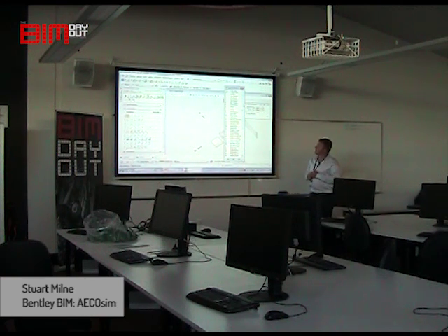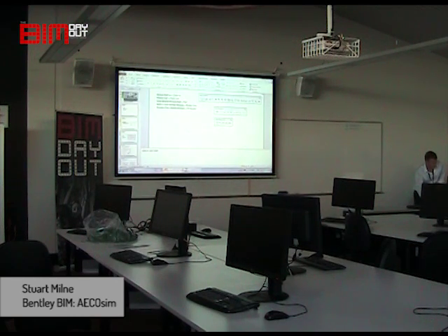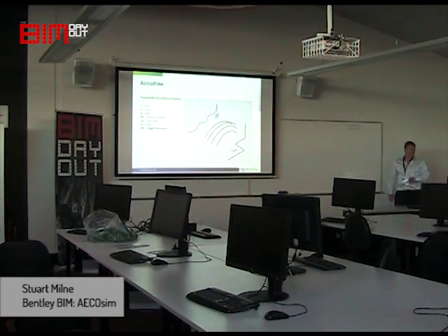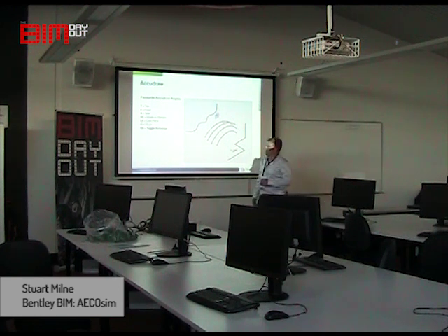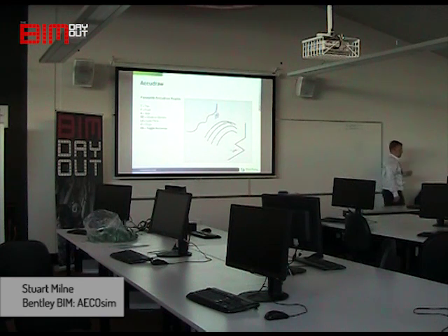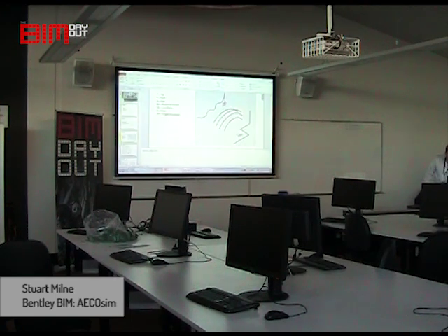Now, we're not going to cover all these. The ones I do want to cover today, though, I want to cover T for top, F for front, S for side. I want to cover RE, which is rotates element. Probably not O for origin. Well, let's go through these four to begin with. Let's see how far we get. Okay.